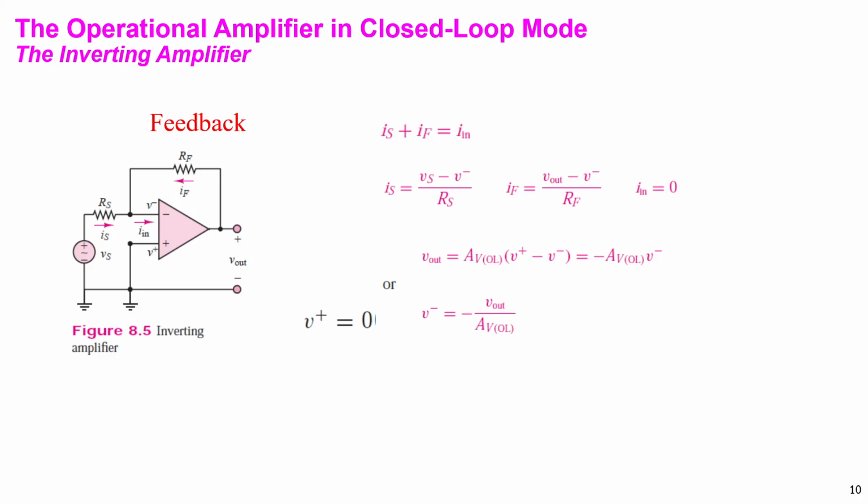So we connect the resistor R_F from the output to the inverting input, the negative input, and then we supply the voltage, and we connect the non-inverting input to the reference value, with this circuit.